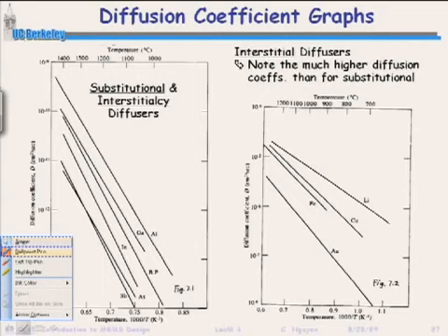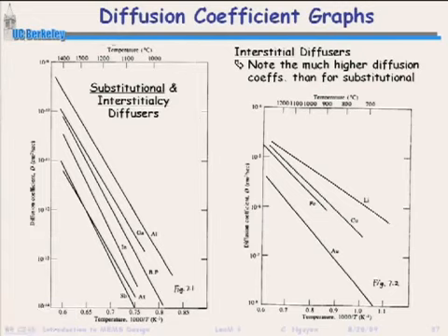And it's going to take very little time and very little temperature for it to do that. And that's why any CMOS process person has to live in utter fear of any gold anywhere around their devices. Okay, so that's why we have these rules in the microlab that there's no gold allowed in any of these tools that have to do with CMOS.